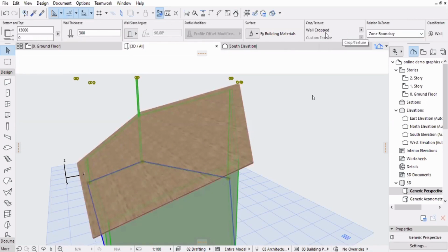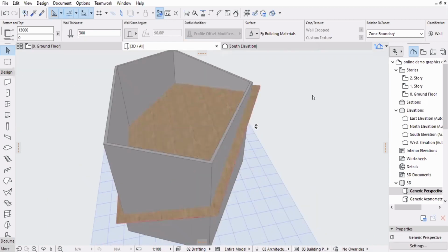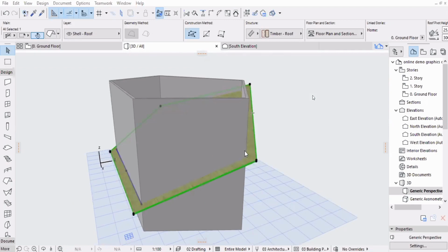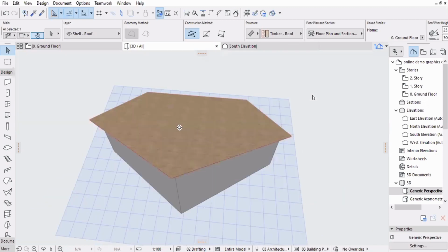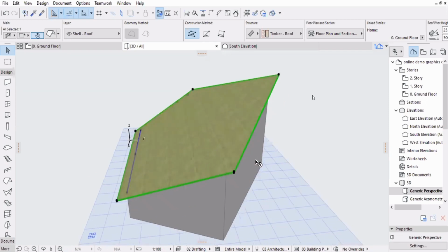Okay. So there's this button called wall crop. You can get it to a stage where it's not cropped. I can undo all the crops. You're getting it? So I've undone all the cropping. Now I can try cropping things again. So crop to single pane roof, and it works, right? Fine. I hope that you understand this. The other way you could do it is increase the overhang first, and then increase the wall height, and then do the trim, right? Are you all with me?